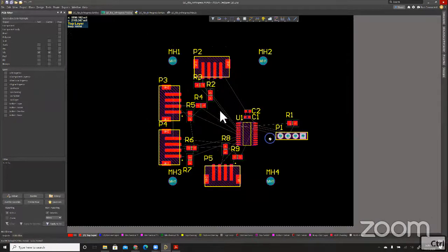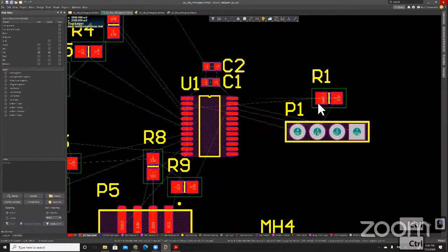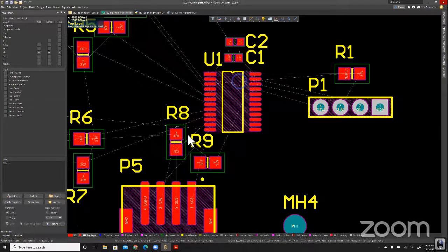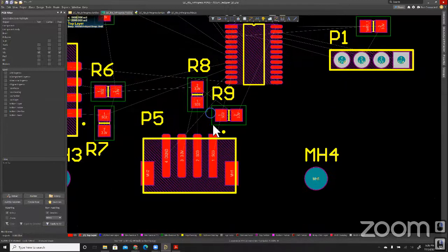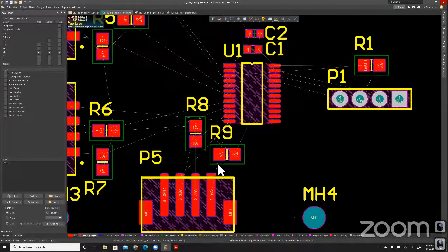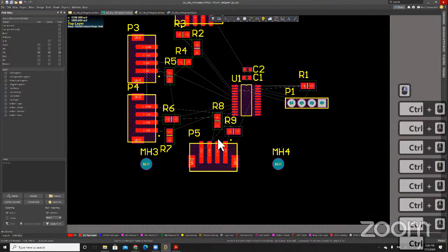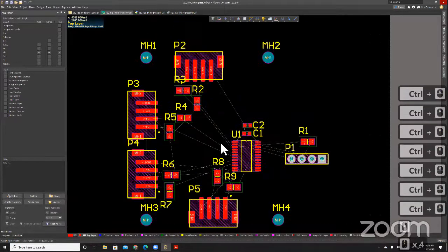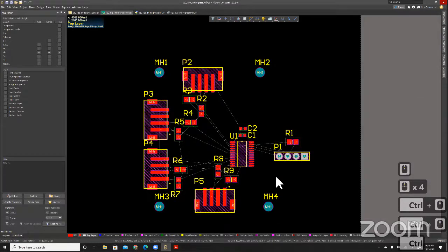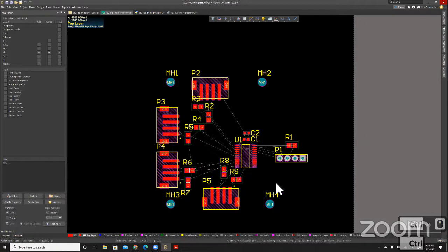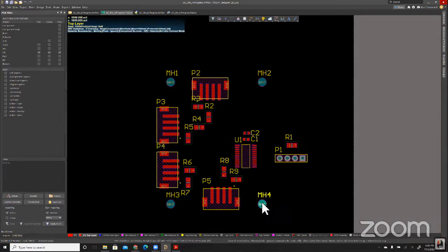So we've got a pull-up resistor for the reset line of this I2C switch near the RoboRio. We've got the resistors and the JST connectors near each other, and in positions that reduce how much overlay or crossovers there are in the rubber bands. But the next thing that's kind of important is to actually define what your board would look like. If you've got your components roughly where you think you want them to be, I've got 4 mounting holes. That one's not quite in a good place.